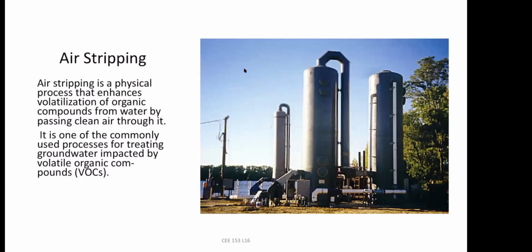All right. So air stripping. What activated carbon cannot do is remove anything which doesn't attach to organic activated carbon, because it relies on the carbon adsorbing those pollutants. There are two types of pollutant that may not be easily adsorbed. First, gases. Some gases do adsorb, such as organic volatile compounds, but many others cannot.